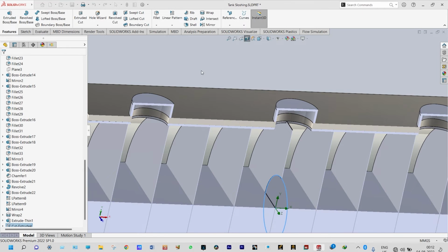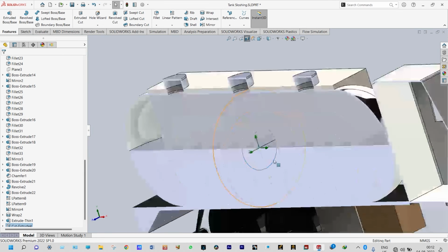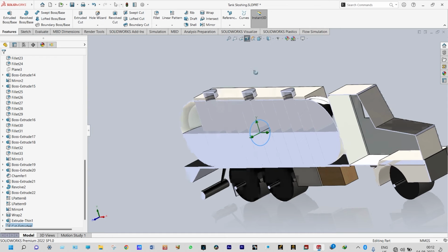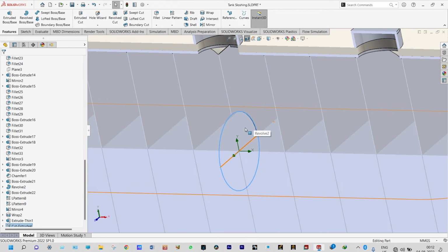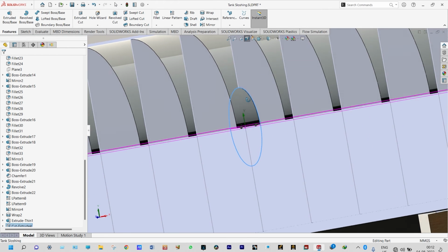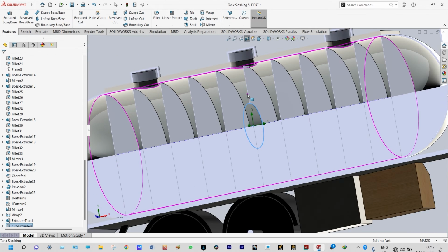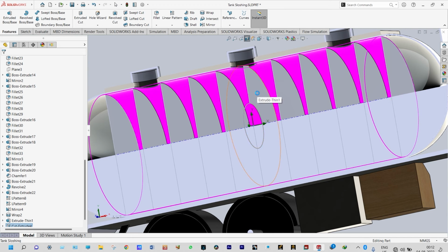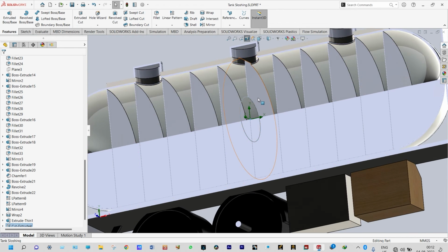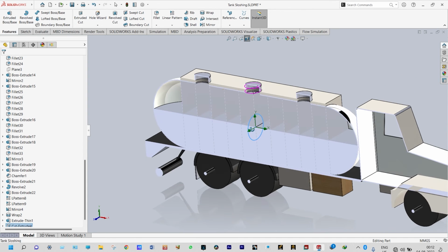Done. One central hole is created at the central baffle. You can see it in a different way. Let us see it. Yes, this hole is clearly visible. Now the thing is, if we use a method like a linear pattern, we will not get the actual design, because the downward wall portion also will be cut.